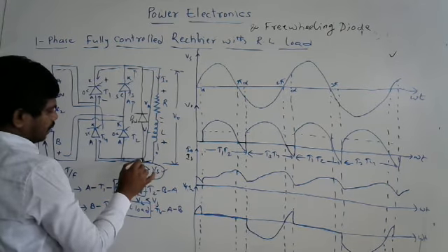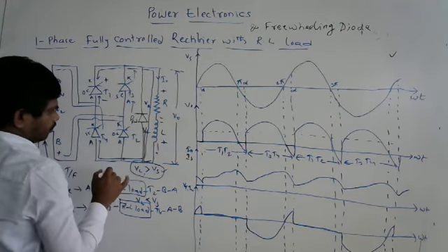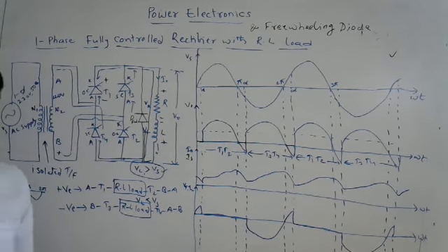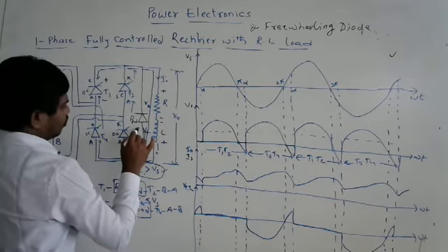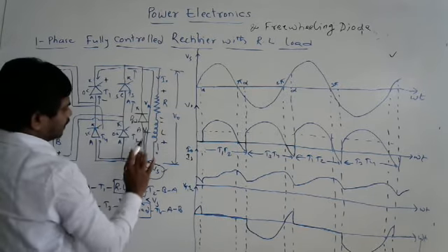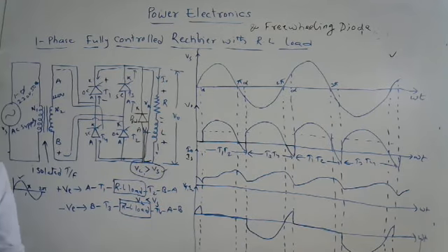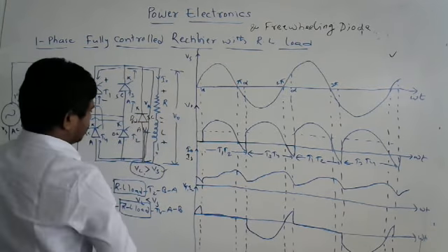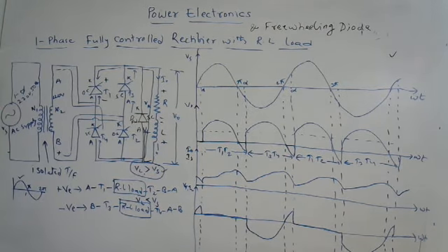Due to that, current is entering the diode first. Since it is an uncontrolled device, it has an anode and a cathode. Current is entering the anode terminal of the device. Hence, it is going to conduct, and we can say it is short circuited. Short circuited, very important, listen carefully.